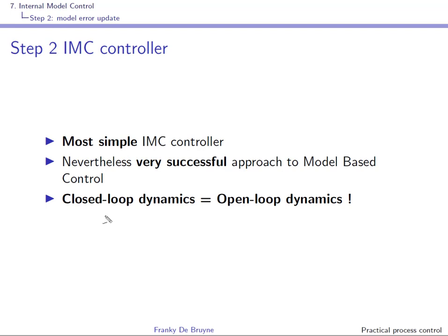What you could do to boost the response in closed loop is do as if the gain of the model is smaller than in reality, right? And what we have seen is this boosting of the MV, and this clearly causes a faster closed loop response.